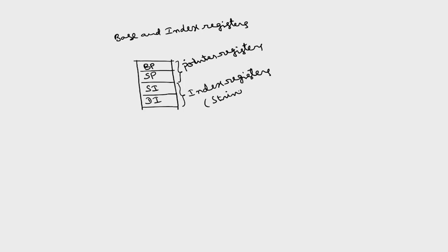I will discuss what is meant by string operations later. They are basically used in string operations. They are used for address calculation, in case of any physical address calculation or stack related operations. The stack pointer is the same as the 8085 stack pointer. The stack pointer always addresses the stack top. I will discuss the details while discussing the architecture as well as the addressing modes and the instructions. And there are some other registers called segment registers.